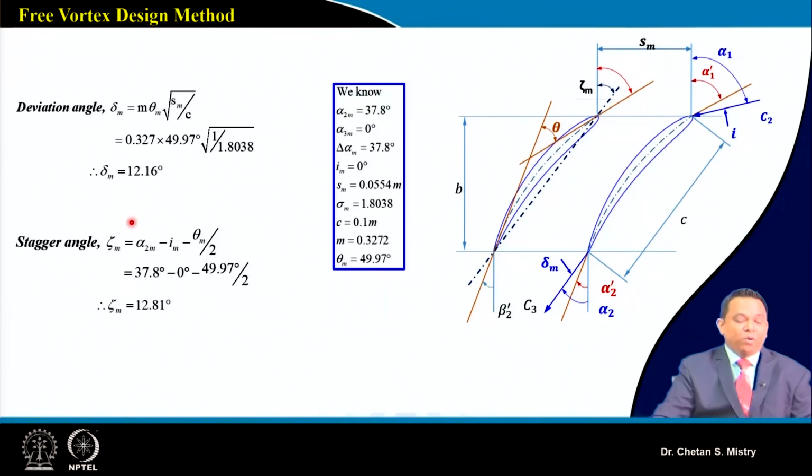Okay. Now, in line with that we can do our calculation for the blade setting angle, or our stagger angle. That is a function of my camber angle, my alpha and my incidence angle. So, let's put this here. It says my stagger angle comes to 12.81 degrees.